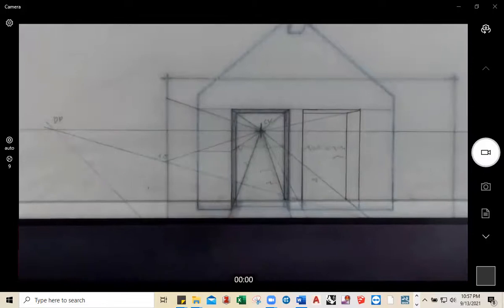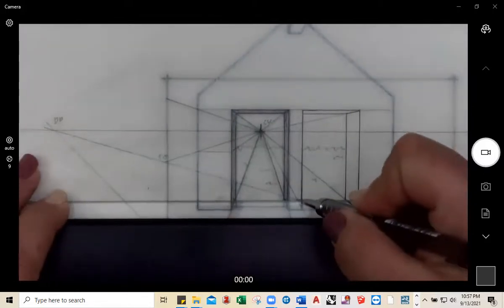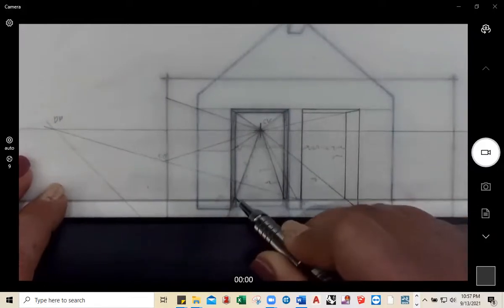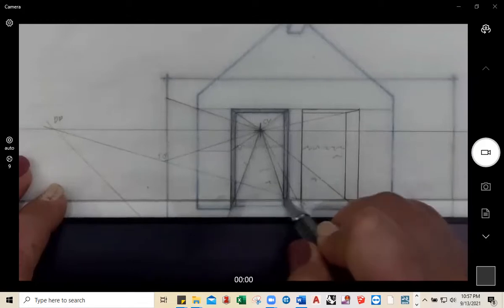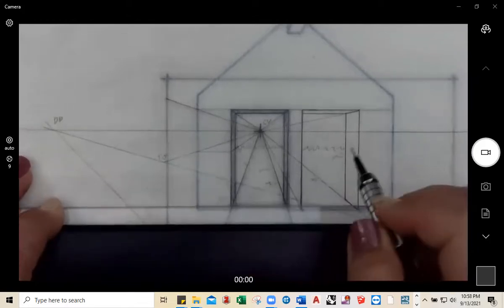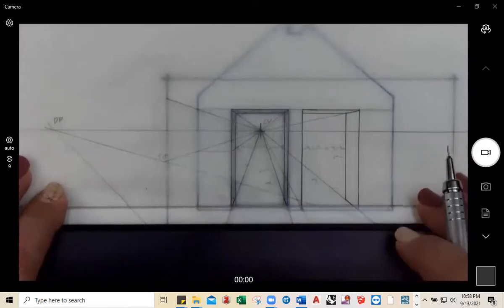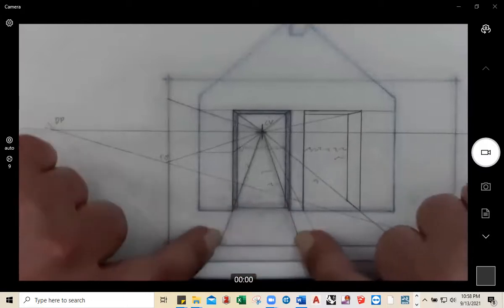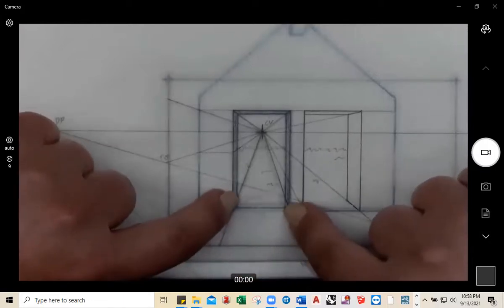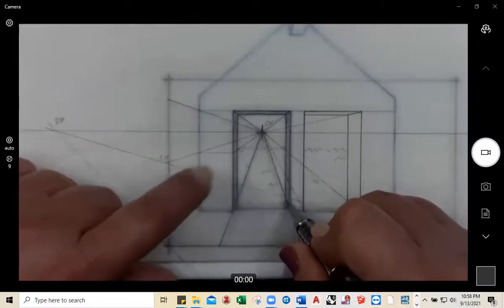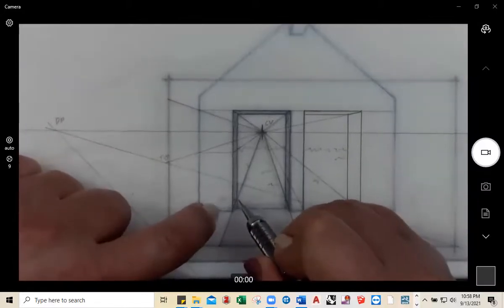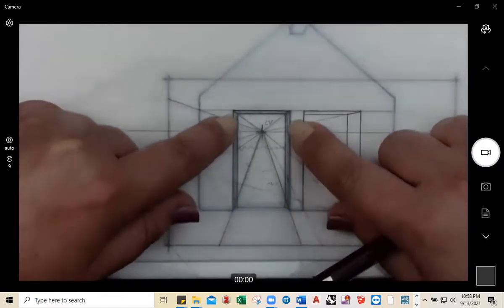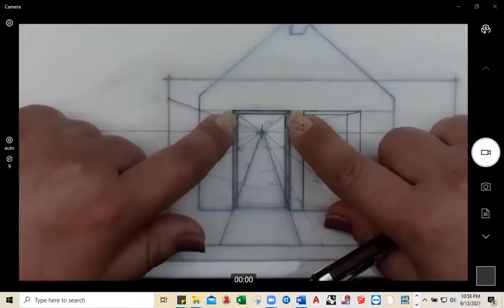What about the left one? Okay, this same intersection where we got this step, you're going to do the same thing. Draw that horizontal line over here to the left as well. So you're going to drop that horizontal line. And where that horizontal line intersects these lines for the opening for your portal, it'll intersect right here and right here. At those 2 points, you're going to go up vertically with your triangle on your parallel bar.